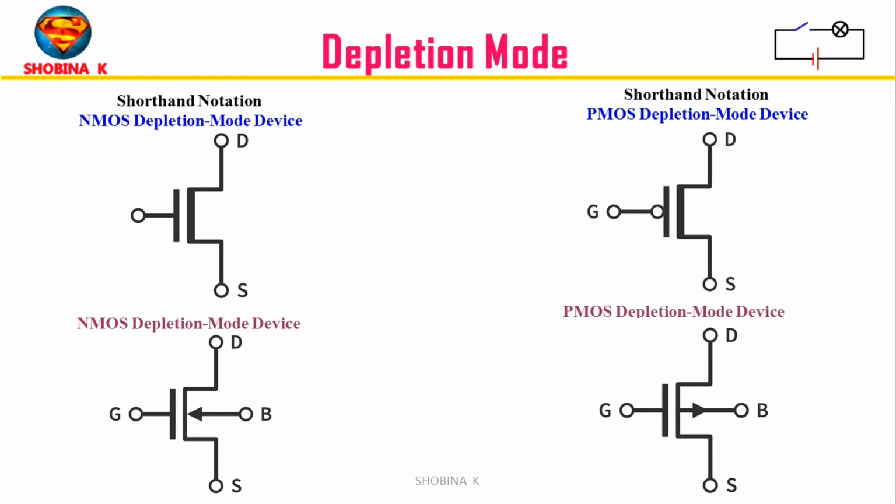Here, why solid lines for depletion mode? This represents a complete or existing channel. The channel naturally exists without any gate voltage. It must be depleted to turn off the device. Deplete means to remove or stop.